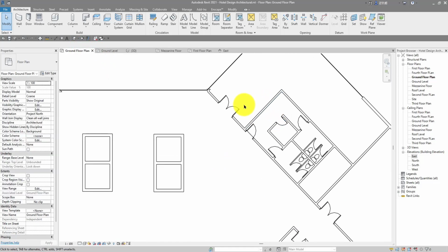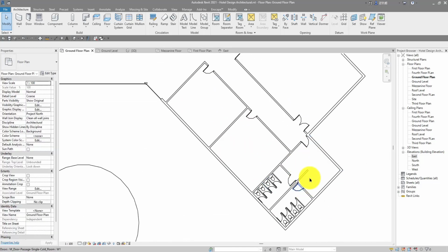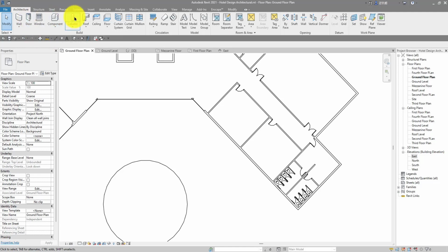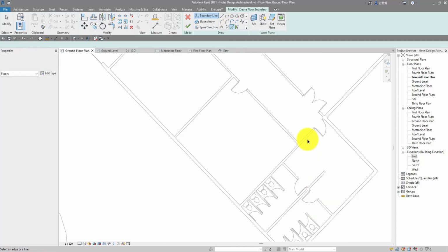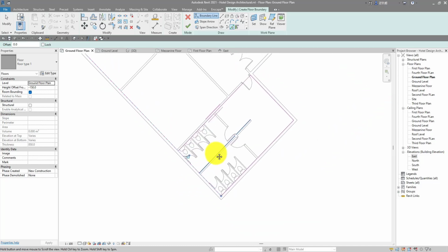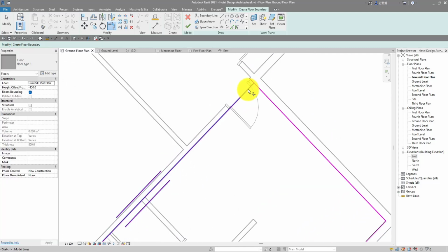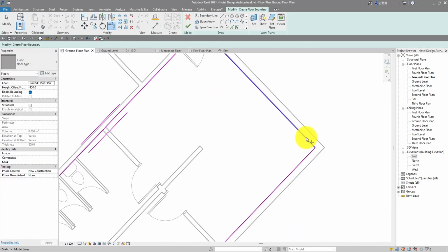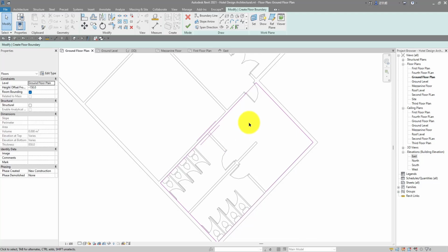So we've created the floor slab. The floor slab type 1 is what we are using for our washrooms. All right, we would want to use the same thing for this area as well. So let's get back into the floor. So this floor type 1, we did that. Make sure it's having a -50. All right, and then just select your pick line 2, and then select this as well, and also this as well. Now hit on TR to trim. Hit on TR to also trim over here. And we've pretty much trimmed everything in here, so it's in there as well.